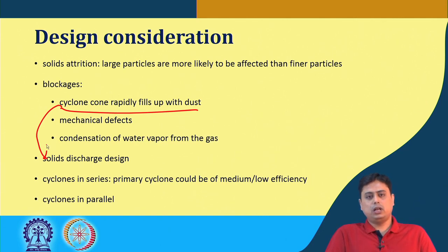This solid discharge zone shouldn't have any leakage, because if this operation is happening under pressure, then any outward leakage, although it can increase the efficiency, means the solids, or pollutants, contaminate the nearby atmosphere. Or if this operation is happening under vacuum, then any inward leakage means the particles that are being deposited can be re-entrained in the cyclone zone.